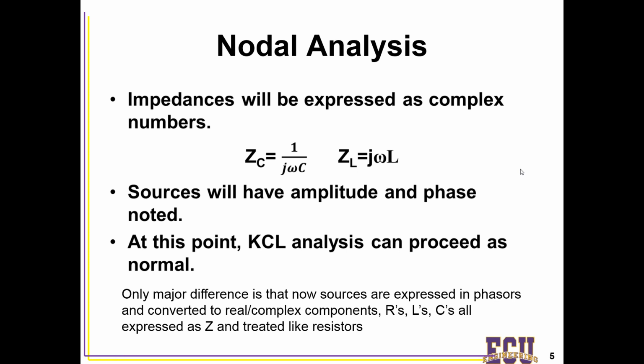It's really the same exact thing, square root of -1 that you've learned in math class. But because i is very commonly used for current, we're not going to be using i, we're going to be using j here. Omega, that is your angular frequency, so we've talked about that previously. And then C is just the value of the capacitance. For inductors, very similarly here we have j omega L.